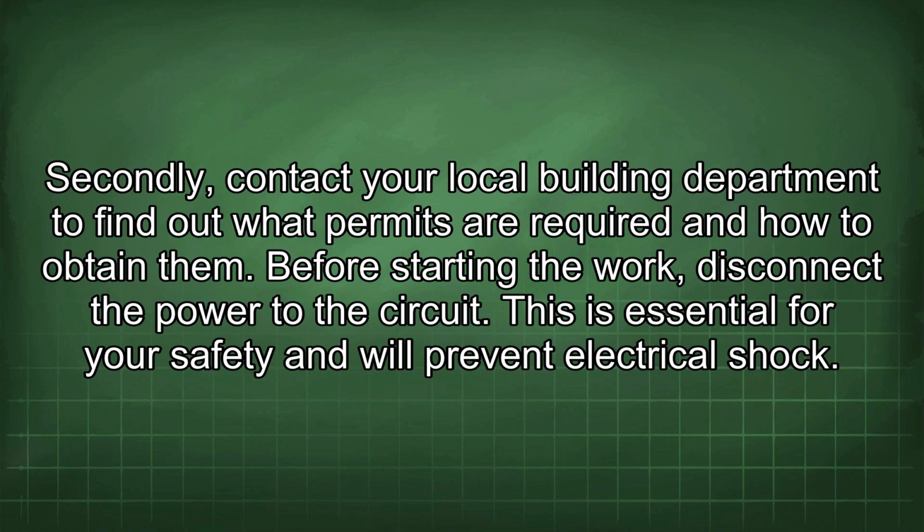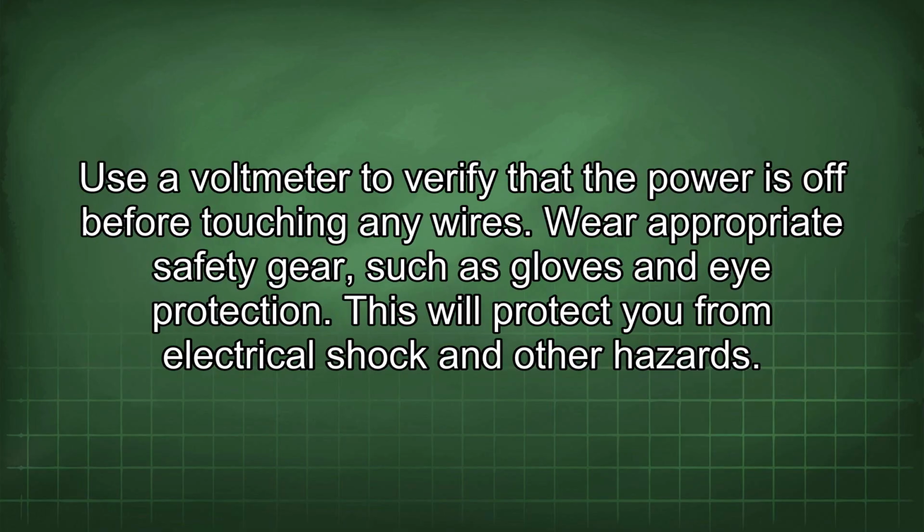Before starting the work, disconnect the power to the circuit. This is essential for your safety and will prevent electrical shock. Use a voltmeter to verify that the power is off before touching any wires. Wear appropriate safety gear such as gloves and eye protection. This will protect you from electrical shock and other hazards.